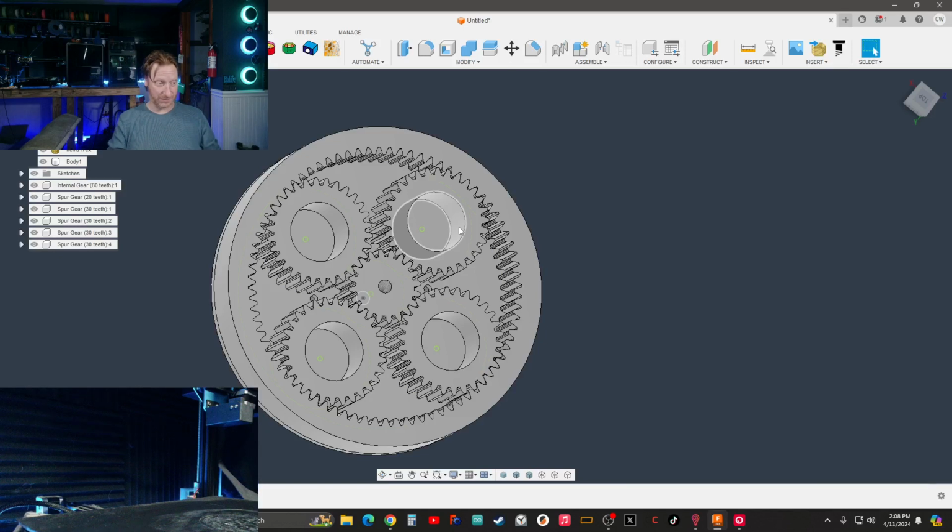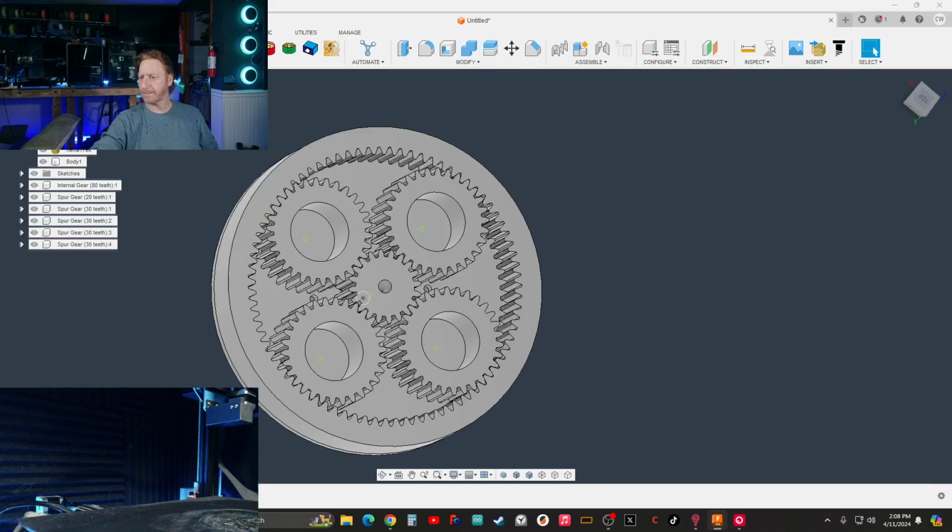So when it comes back, we know where it starts, the starting point, and then we can count the amount of steps to do a rotation to move the arm like 180 degrees. These motors are 1.8 degrees per step.